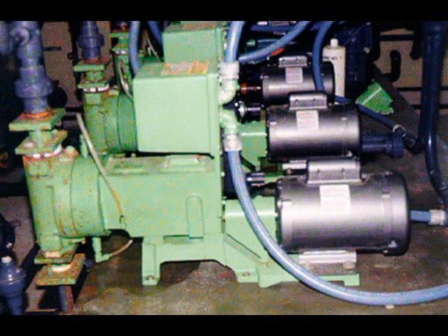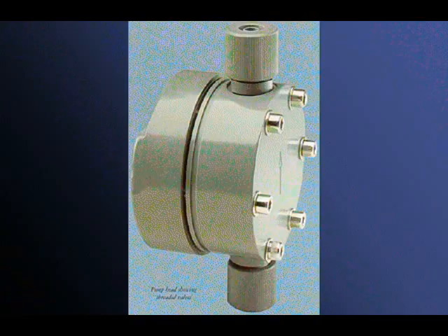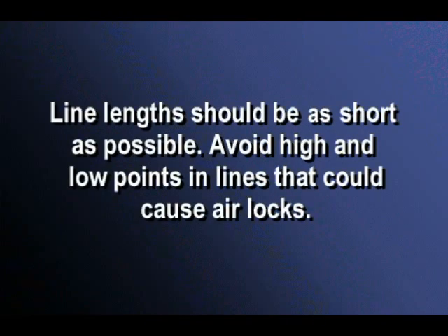If the pump is not mounted properly, gears may not lubricate properly, and the pump might fail. 2. Are the suction and discharge valves vertical? The valves will only work when they are vertical, and the valve seat is at the bottom. 3.